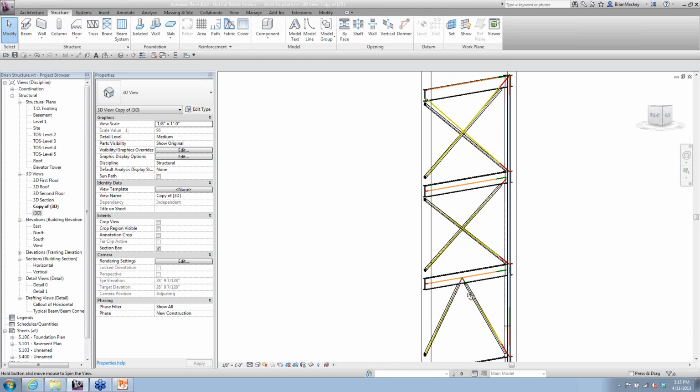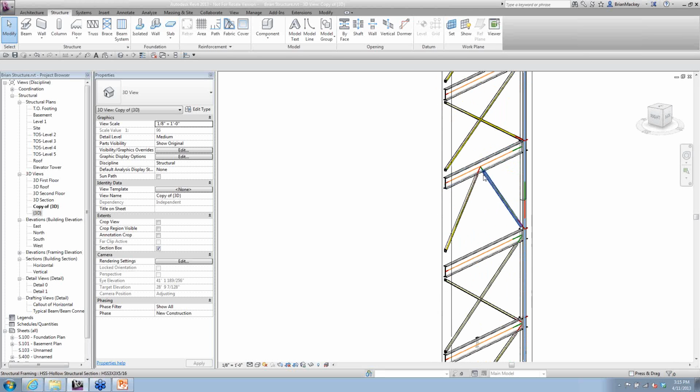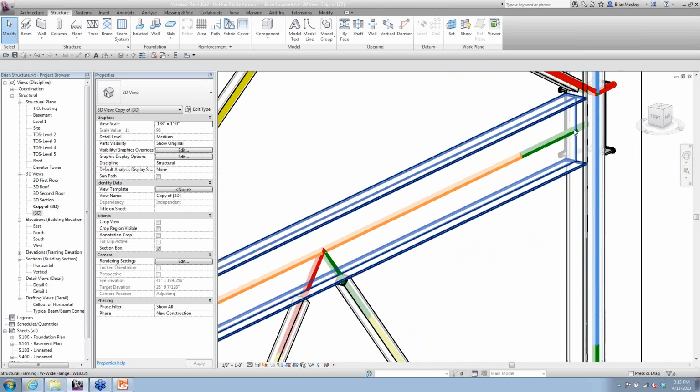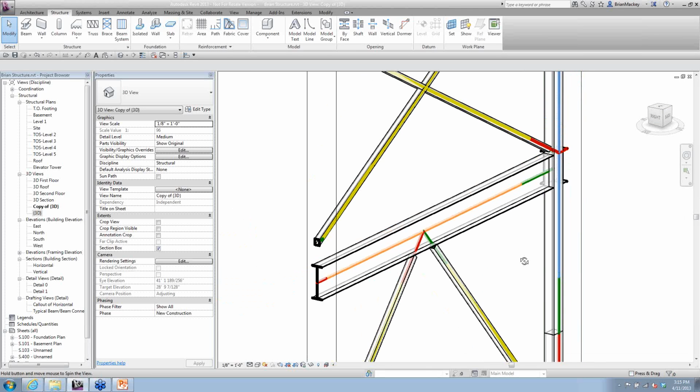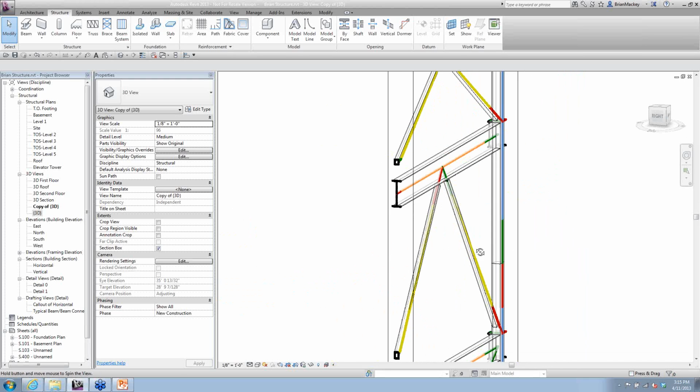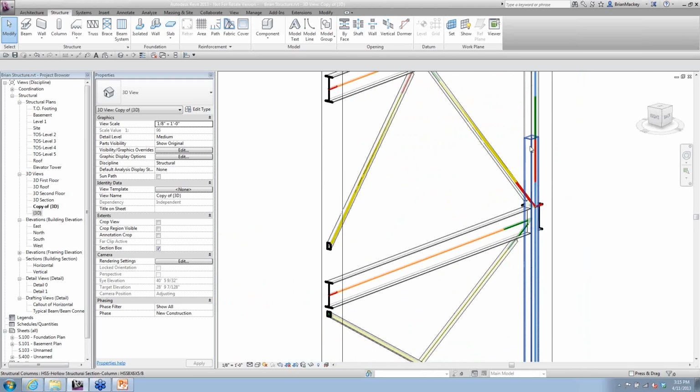And you might be wondering, well, what the heck is going on? Why did my brace frames and my beams bounce to the outside of where the columns are, as opposed to being in the center? And actually, it doesn't even look like all of them did it, because these ones are actually centered. So the reasoning for that is there's a chain effect as we start looking at that auto detect.